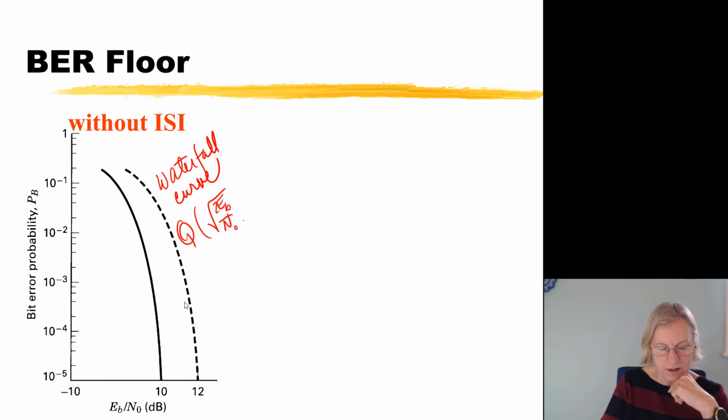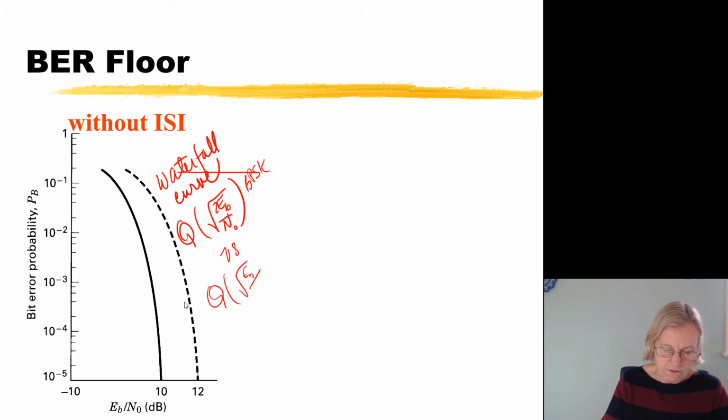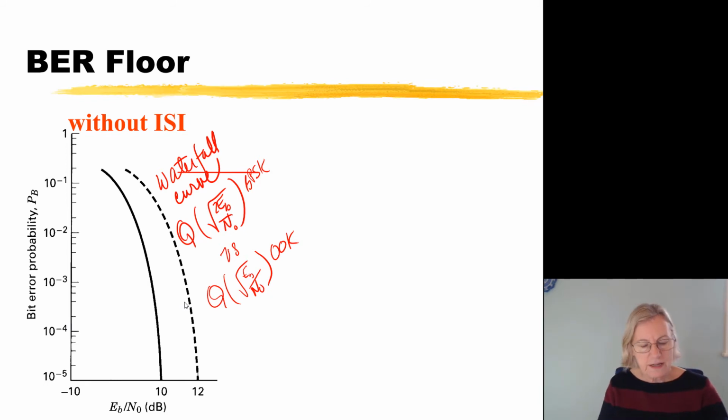For instance, for BPSK, we had this curve. And these curves, I guess we had BPSK and we had on-off keying, and we compared those. Those are the first error curves that we had to look at. And these have this typical waterfall characteristic. And this is because we assume that this is a system where the signal is not crushed by noise, that in fact we can have the transmitted signal have a matched filter and that there's no distortion introduced, and then we would have this performance.